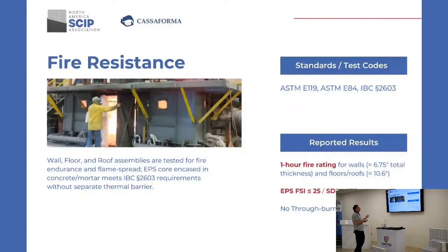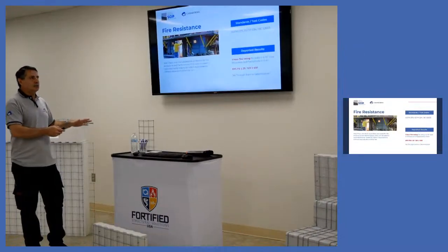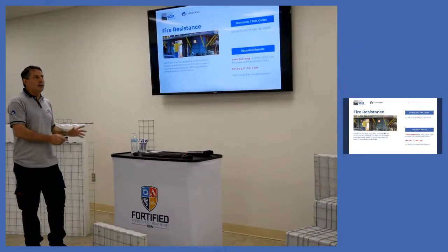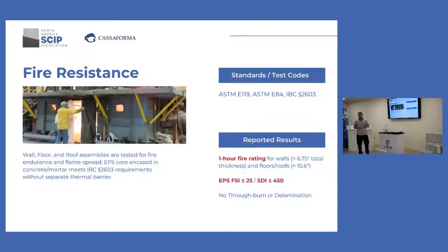Well, here we are showing the fire resistant tests. I have to say once more that this is about the thickness of the mortar that you apply. And usually the tests have been run with loads, so we ensure that 2 hours are with loads on it.